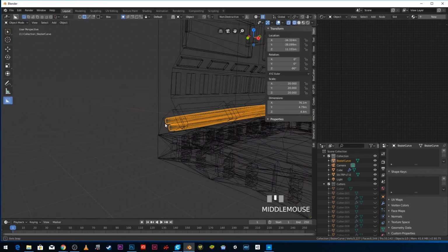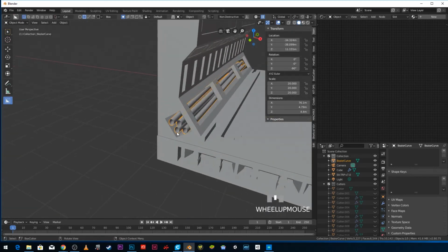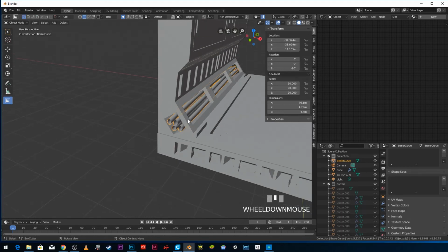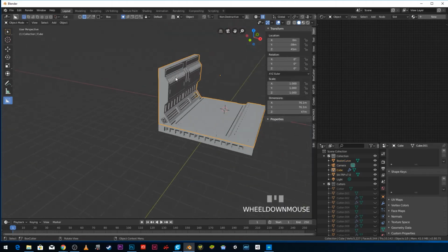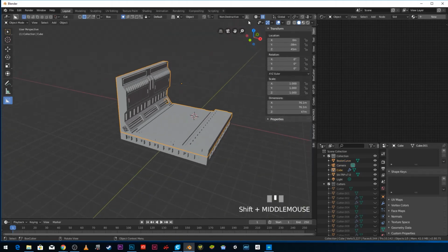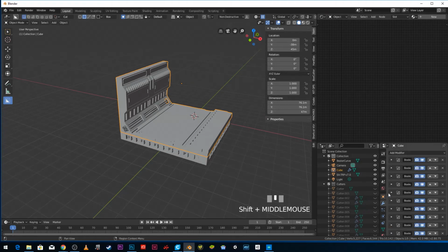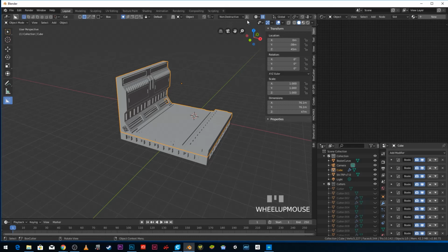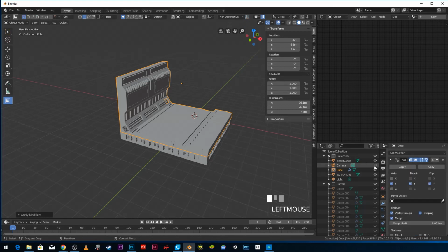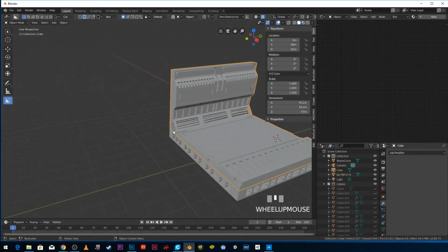And then finally, I'm going to put in this little cube here at the end to kind of seal this piece. The easiest way to do that is actually use this itself. So I'm going to, if we look over here, we can see all of the Boolean actions we've put on this. So I'm going to apply them, and then I'm going to apply the hops mirror.